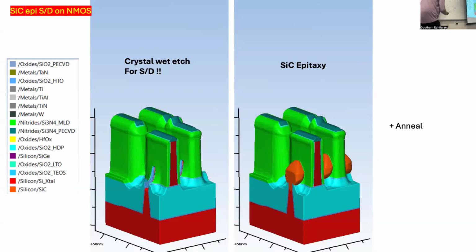So if I put silicon carbide, which has a lesser volume than silicon because it has less density, it's going to have tensile stress. But silicon germanium is bigger, right? So it's actually going to compress it. So it depends on which type you use. And it turns out that if you do compressive stress, it actually increases mobility of the holes. But if you do tensile stress, it increases mobility of the electron.